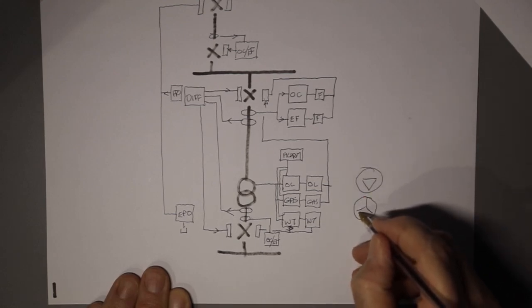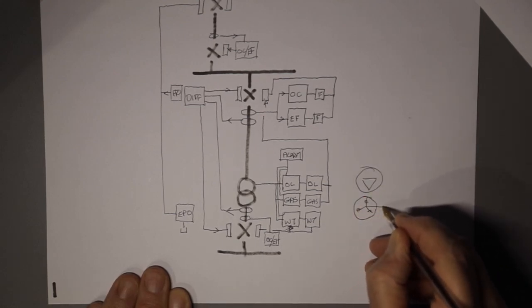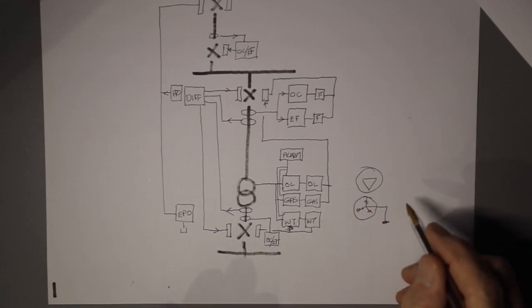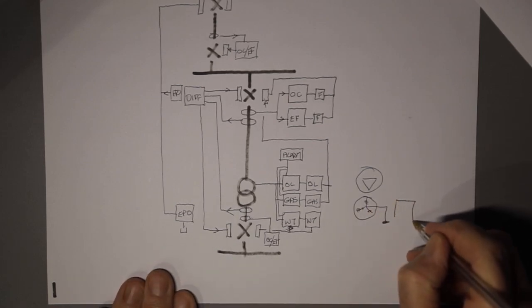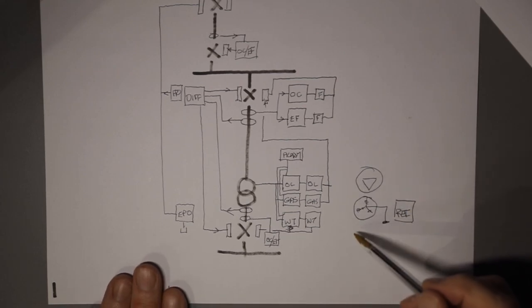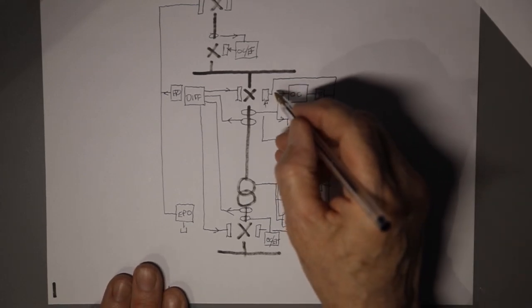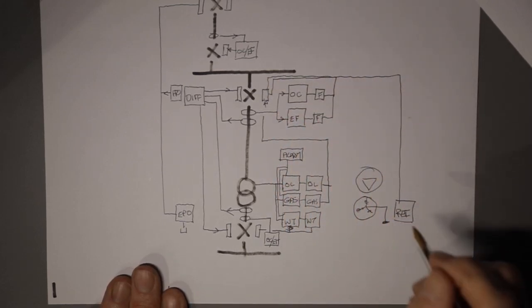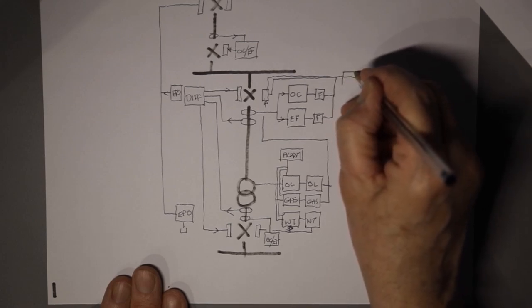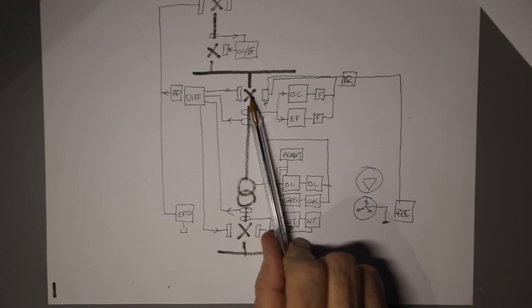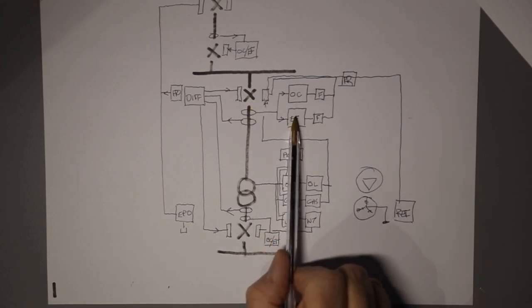Now if this was restricted earth fault, we'd have 3 CTs on the windings and 1 on the neutral. Now what would you want the restricted earth fault to do? Well, it's restricted because it's between those 4 CTs. So that goes into the restricted earth fault. Now it's no good just tripping the LV side, because it's a fault on the transformer, and tripping the LV side wouldn't do anything. So what we would do is get the restricted earth fault to operate the shunt trip coil on this circuit breaker,